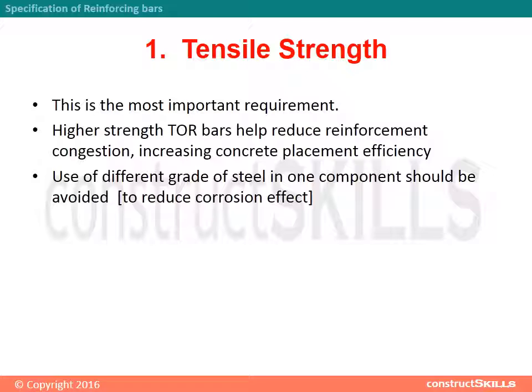Higher strength Tor bars help reduce reinforcement congestion, increasing concrete placement efficiency. Use of different grades of steel in one component should be avoided, to reduce corrosion effect.